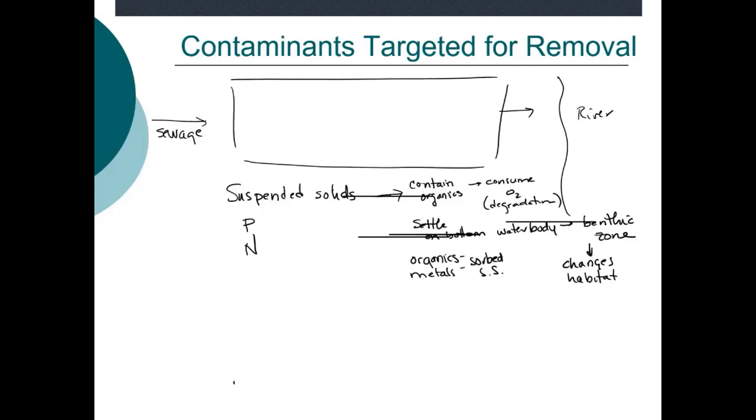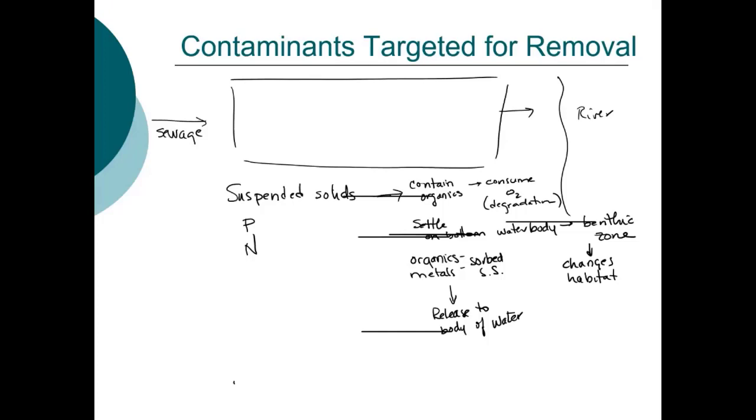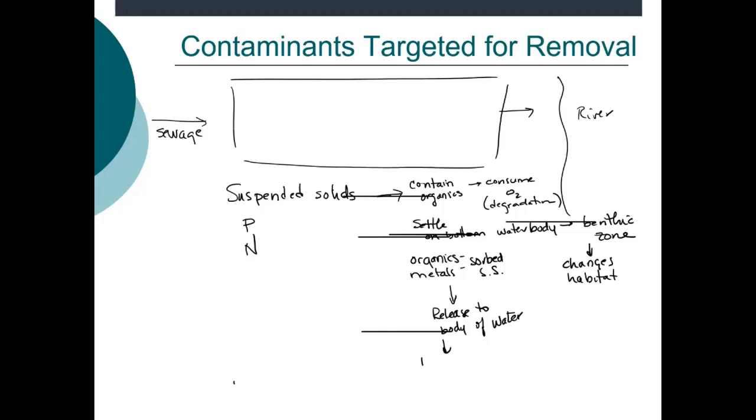If you don't remove those, then you're potentially releasing those organics and metals to the receiving body of water. Over time, those metals can dissolve, they can be released, they can be bioaccumulated. If they settle, then you've got benthic organisms, and those metals can potentially bioaccumulate. Same with organics. For that reason, we don't want to release suspended solids.